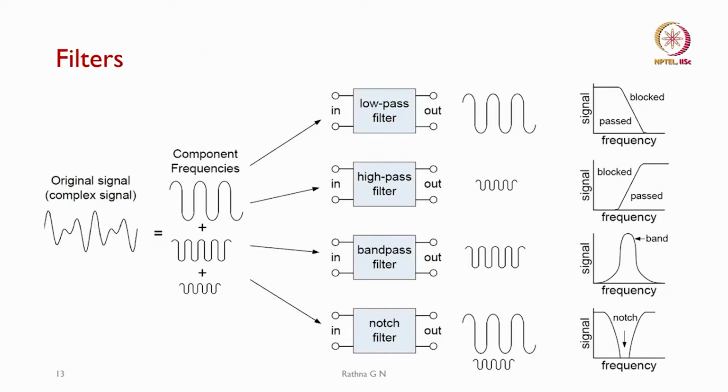So, later on we went on to define our filters. We said the common filter: this is the original signal, and then you have multiple components added with it, and either we can do low pass filtering to get one of them, or do the high pass filter to get multiple of them, or I can select one of them with a band pass filter, or I can use notch filters so that I eliminate these two and get one of them.